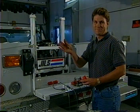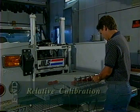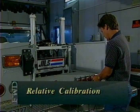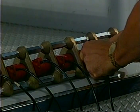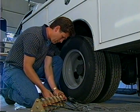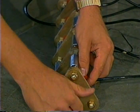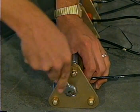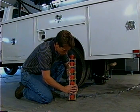Now we'll use a third type of FWD as we take a look at the next phase, relative calibration, where you arrive at even more precise correction factors for the outputs of your sensors. In relative calibration, you put all of your FWD sensors in the test stand that you brought to the calibration center. As we discussed before, the idea is that with all of your sensors stacked up in the stand, they can all measure the same deflection all at the same time.